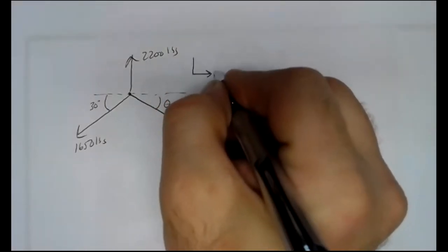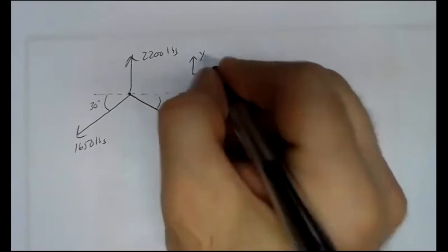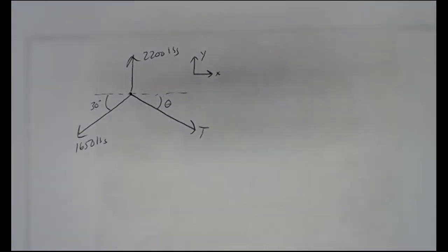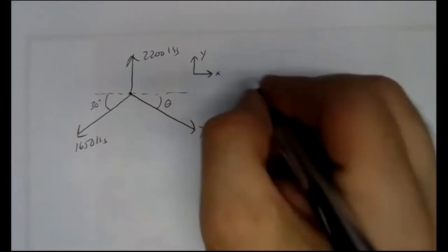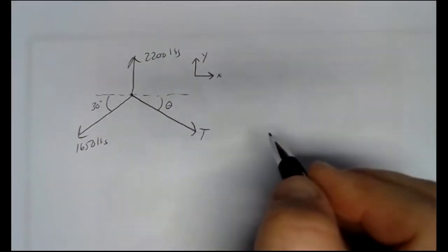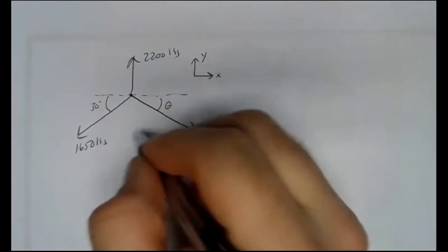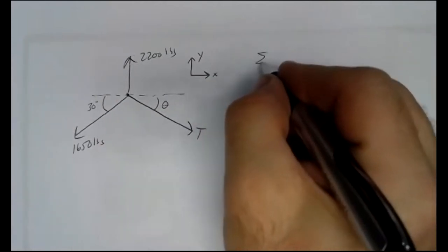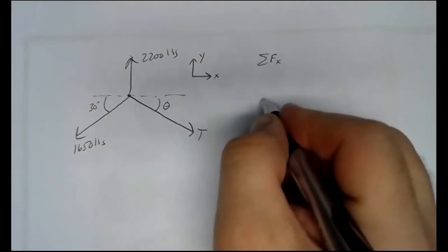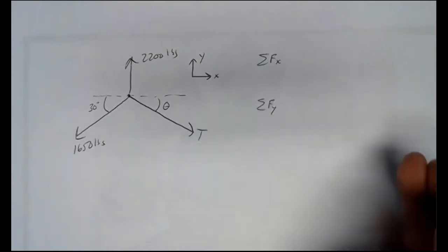We'll draw a coordinate system. And these might be a lot easier to look at now, by the way, after you've all been through truss analysis and method of joints and all of that. This was basically the fundamental problem in method of joints, was to figure out your equilibrium of a concurrent force problem. So here we've got our coordinate system, and we can break up the vectors and do our sum of forces in the x direction and our sum of forces in the y direction.